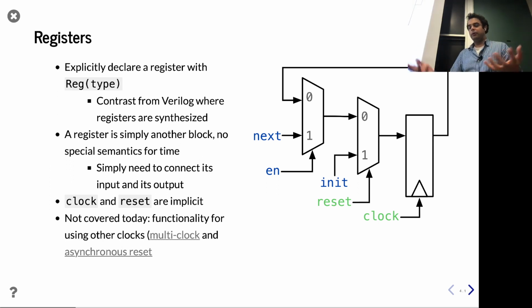But you can think of it as qualitatively having this impact. For example, if I have a reset signal, it doesn't matter what the input is; the register gets set to the reset value. Or if I have a write enable and the write enable is 0, it doesn't matter what the input is; I keep storing the same value I had originally. After the write enable is on, then of course it takes the new value, the next value.